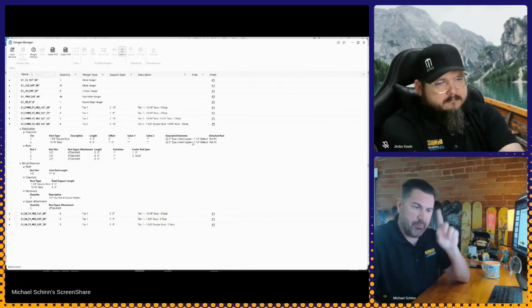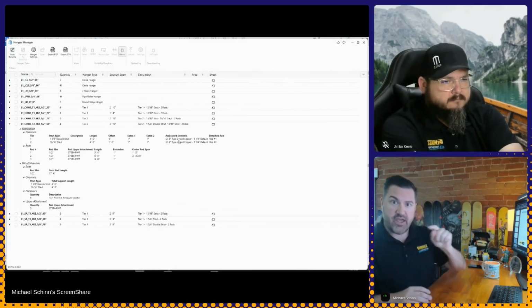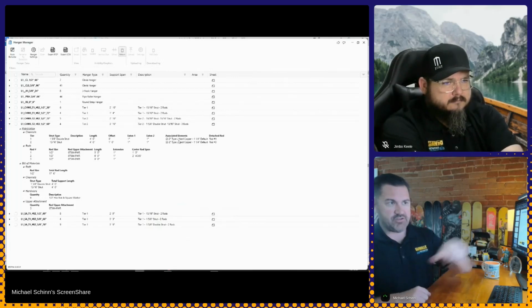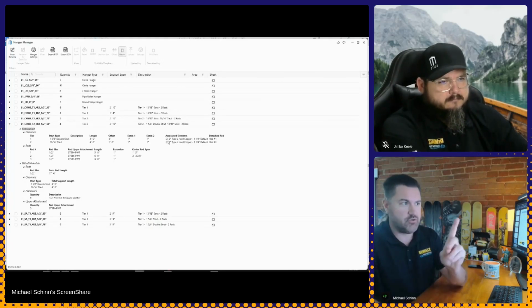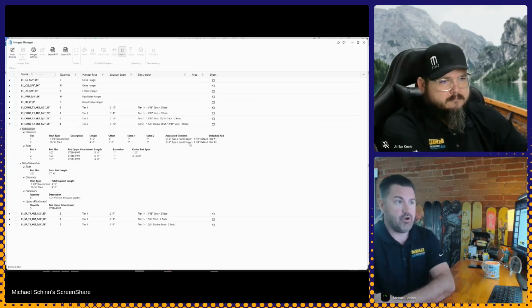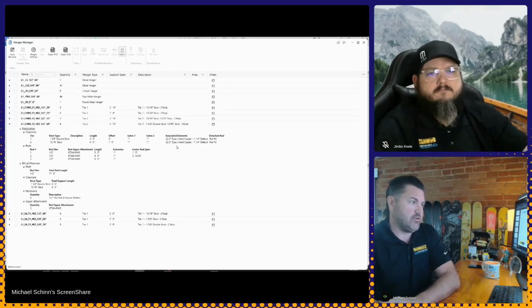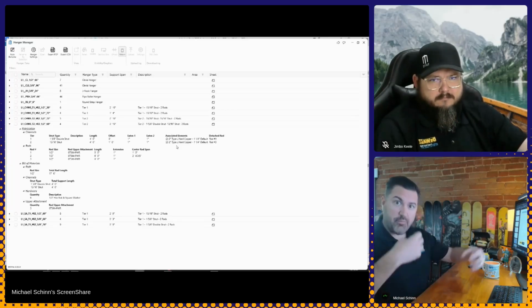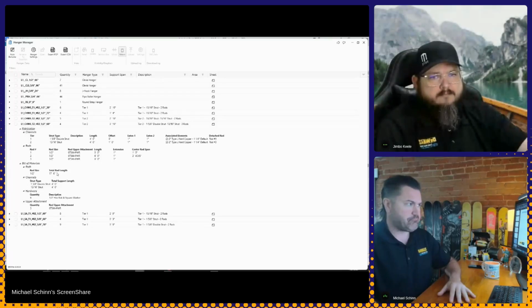Remember I mentioned earlier about the point loads. How are we going to be able to do that? Notice that every hanger knows what every pipe is associated with, as well as down to the trapeze on what elements are on what tier. We know there's 2 2-inch copper hangers on tier 1 and 2 of them on tier 1 and tier 2. That way we can start getting proper point loads in the near future. Your rod sizes and everything.